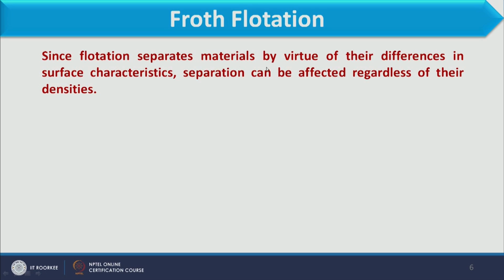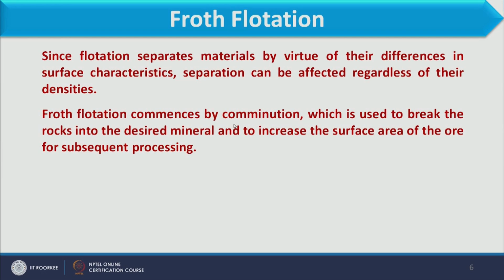Since flotation separates material by virtue of their differences in surface characteristics, separation can be affected regardless of their densities. So, the density of the compound will not affect the separation process, only the surface characteristics of the compound will matter. Froth flotation commences by comminution, which is used to break the rocks into desired minerals and to increase the surface area of the ore for subsequent processing. So, first of all we have to crush or grind the mineral, grind the rock, and then the small particles will be used for the flotation process.